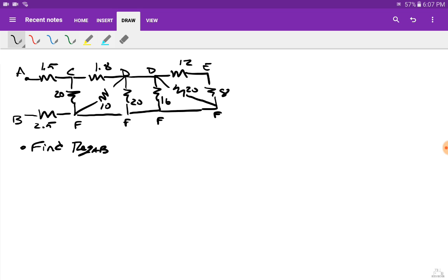So we have this huge thing, and then they say very specifically, find the equivalent resistance of this mess between A and B. Now, remember, whenever you're shrinking your circuits, or trying to reduce a circuit between something, they always have to tell you where you're reducing between. In this case, they say find it between A and B. Remember, A and B are your nodes of interest. They're basically functioning like the addresses of what you're looking for. It's like saying, oh, come to my house, and then I never tell you the address to my house. You don't know where to go.